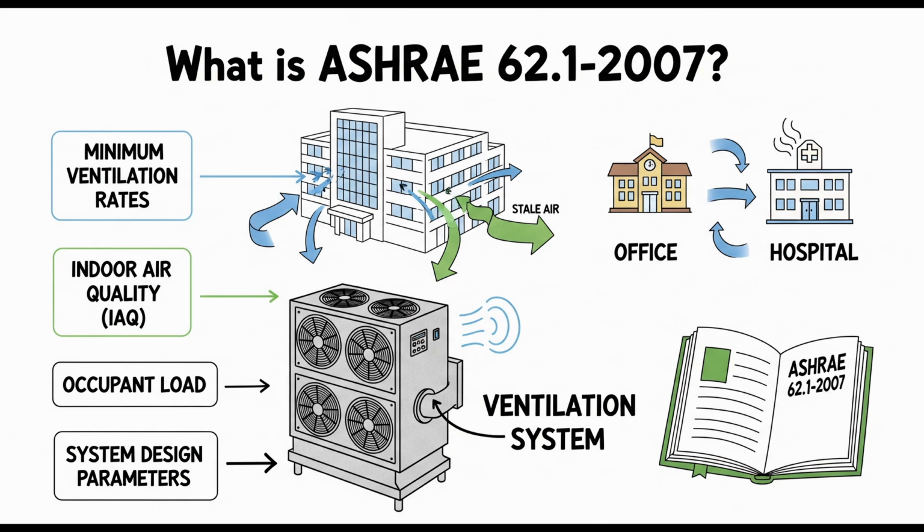Access to what? To everything. Air handlers, ducts, filters, cooling coils, drain pans, fans, sensors. All those components need to be reachable for inspection, cleaning, and maintenance. That makes sense. Because if you can't get to it, you can't maintain it. And poor maintenance pretty much guarantees poor air quality down the line. That seems so simple, but yeah, incredibly practical.